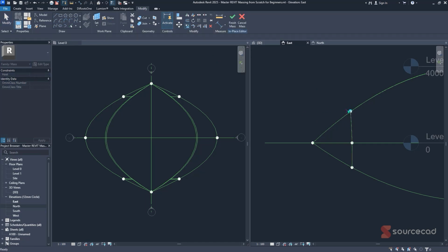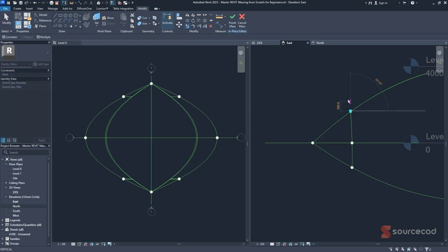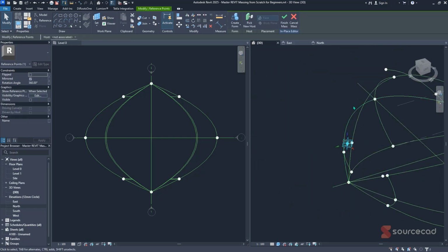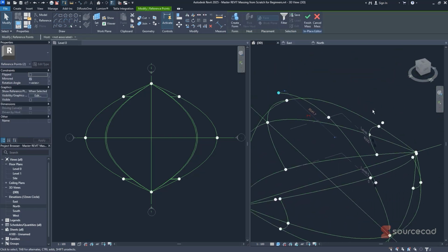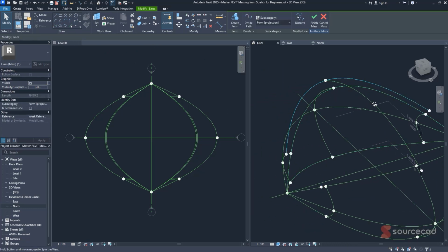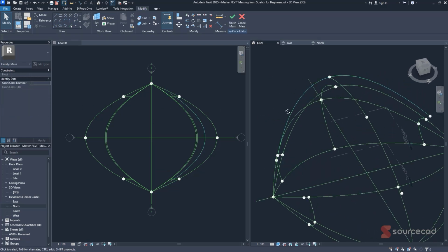So I'll just create my dash window here, then click on copy. Then after that's done, I'll just eyeball my area, let's say to 600, something of the sort. And once that's done, it's just a matter of connecting them. I'll select this point here, this next point here, and this last point here. And if I just click on this option here, just like that, we have this specific curvature that has been created, and I want it to be a reference line as well.